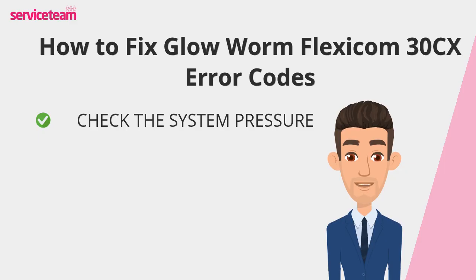Low pressure is a very common cause of lockouts, so this simple step often clears the error. Sometimes the boiler just needs a reset. Turn the power off, wait around 10 seconds, and turn it back on. If the fault was only temporary, the code should clear. Keep an eye on the boiler afterwards to make sure it's running smoothly.